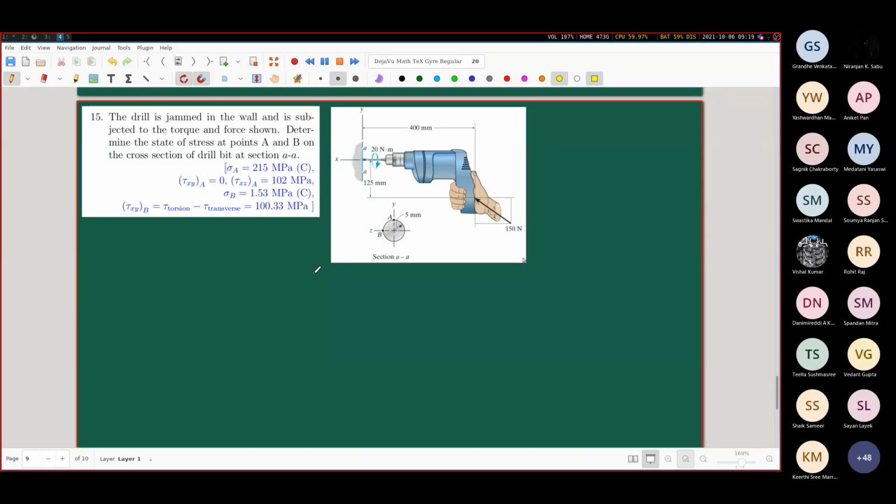But in terms of the resolution of the forces and the moments, this is a two-dimensional equilibrium problem. And for a two-dimensional equilibrium problem, what are the equations that we have to use? The static equilibrium equations. What are they? Tell me. Sigma Fx equal to 0, sigma Fy equal to 0, and sigma M of a suitably chosen axis equal to 0. Alternatively, that is not the only set of equations you will have to follow.